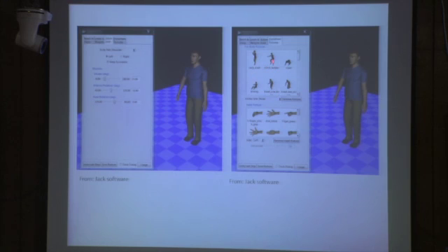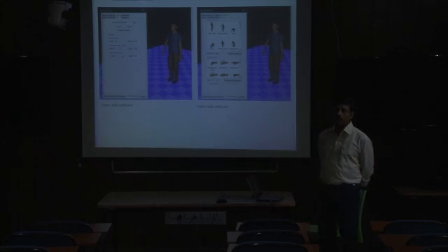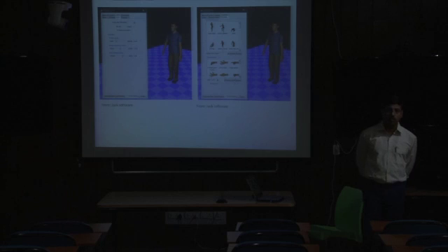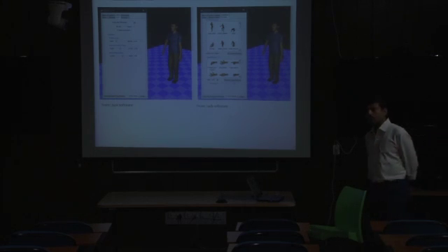Moreover, in JAX software, apart from this type of standard posture which you can directly go for, even for individual segments like hand, you can give specific type of posture like grasp, grip, pointing. This type of hand posture also you can directly provide to the digital human model. Otherwise, in most of the software, what you have to do, individual body segments and its associated joints you have to manipulate as per your requirement to make your simulated working task.